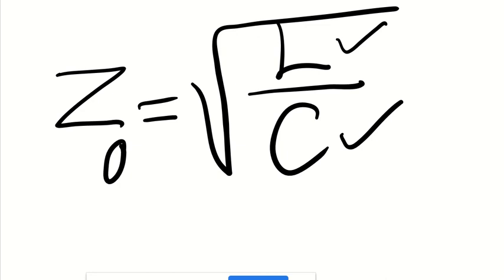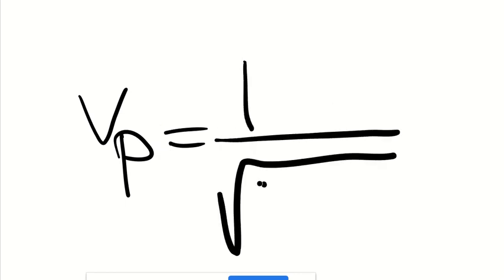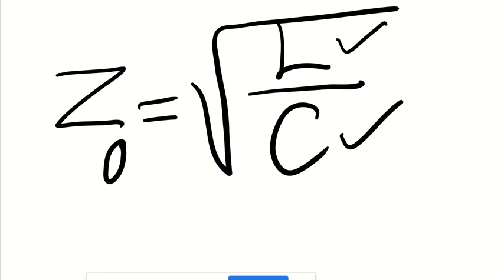And the propagation velocity equation is, as I said, inside the transmission line, because of its permittivity and the structure inside, the velocity is less than the speed of light. So I define it as Vp, and for the transmission line there is a formula you can plug in, and of course it depends on L and C. Okay, so this impedance, maybe you have heard about it.